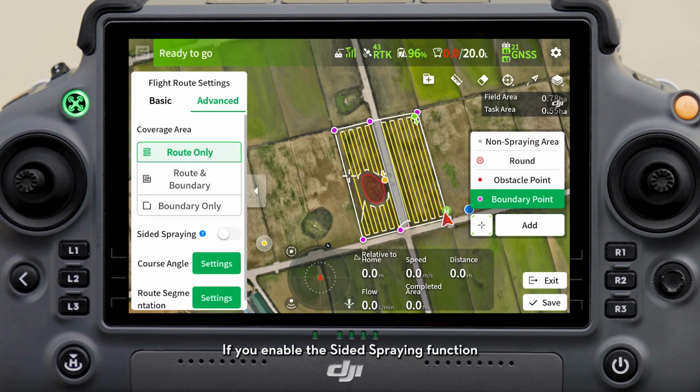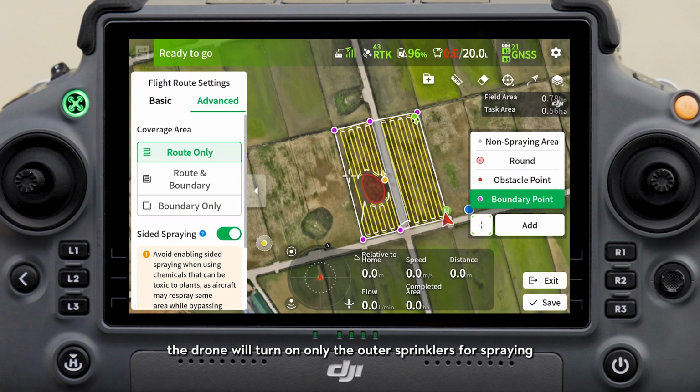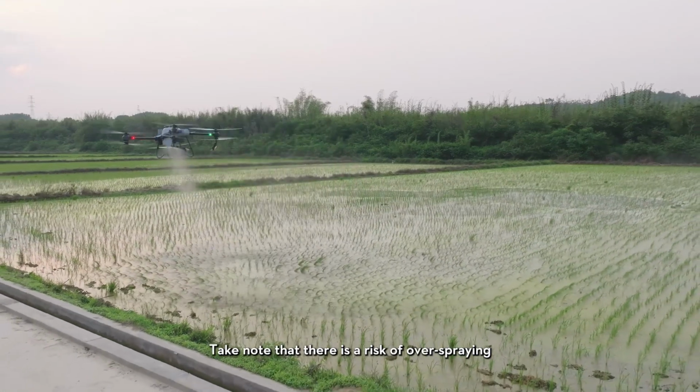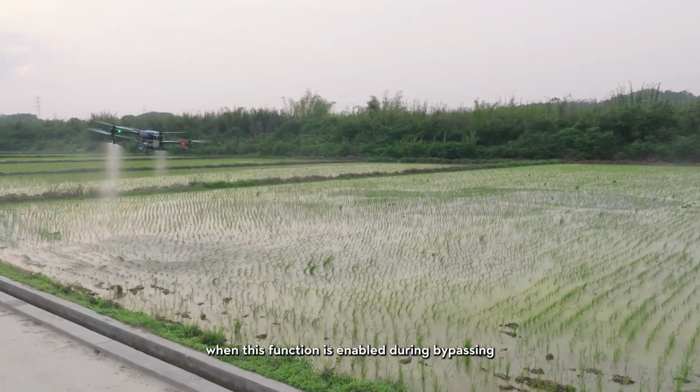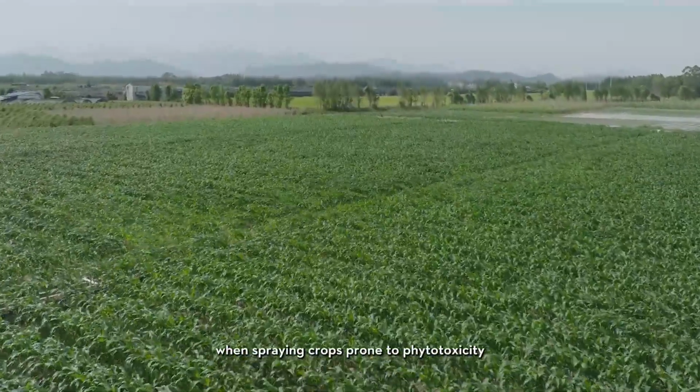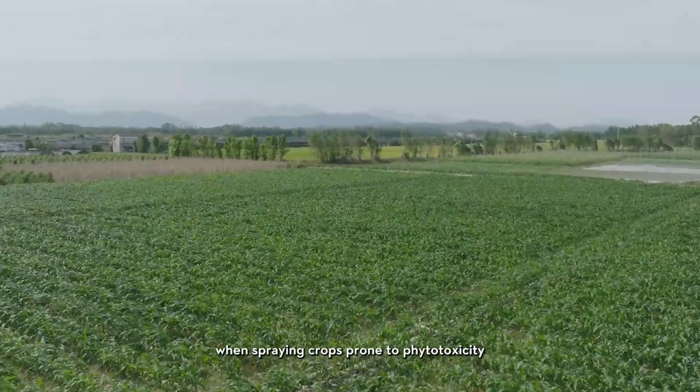If you enable the sided spraying function, the drone will turn on only the outer sprinklers for spraying during lateral movement or turn on only the inner sprinklers during bypassing. Take note that there is a risk of overspraying when this function is enabled during bypassing. We recommend that you do not enable this function when spraying crops prone to phytotoxicity.